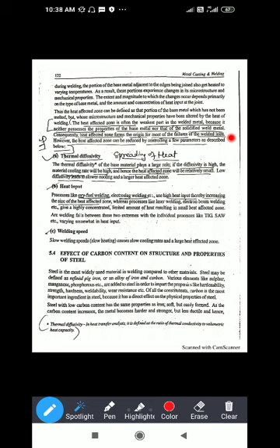If a 10, 20, or 30 mm spot is to be welded, the surrounding area is also affected by the torch flame. But in electrode welding only the rod is used and the particular area is welded, not all the area. So compared to arc welding, the heat affected zone is more in gas welding.